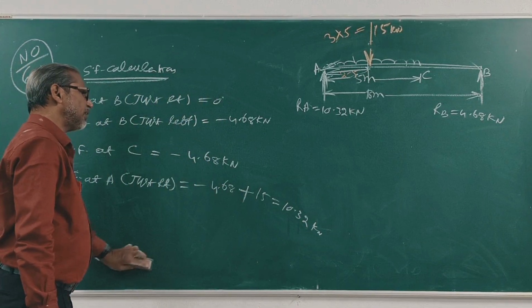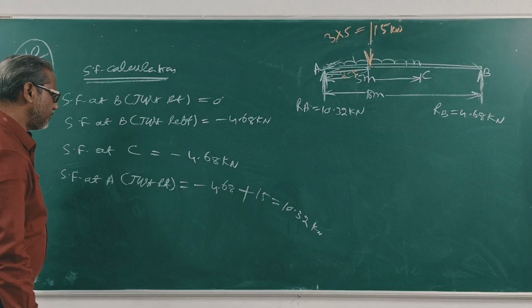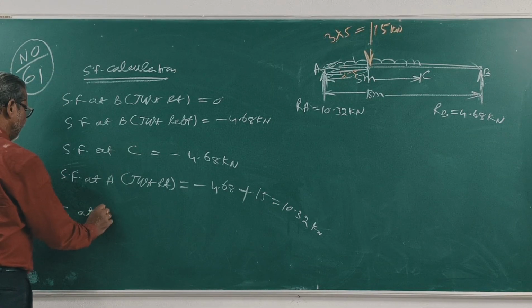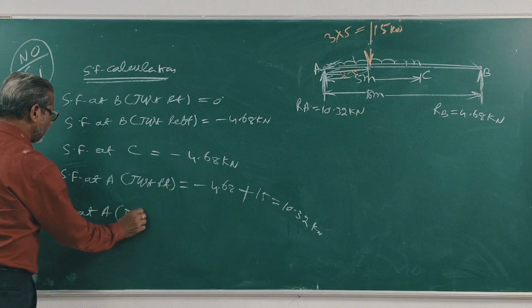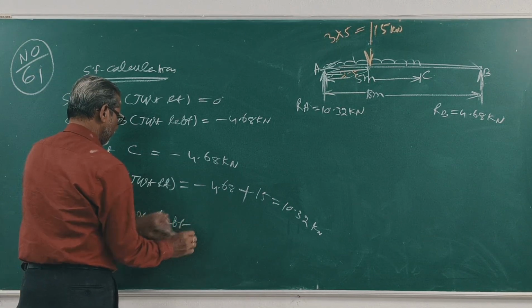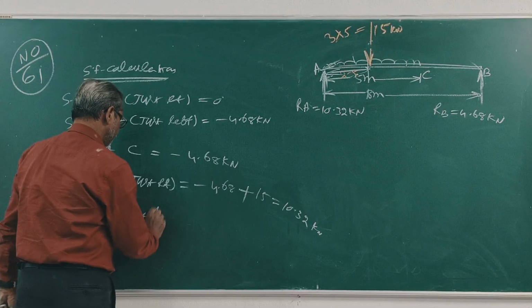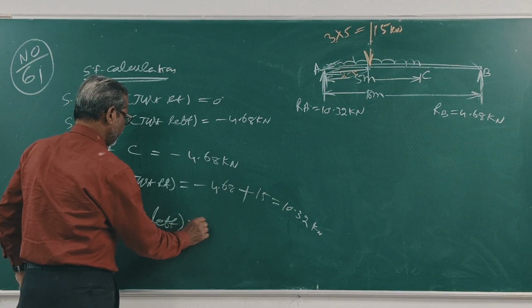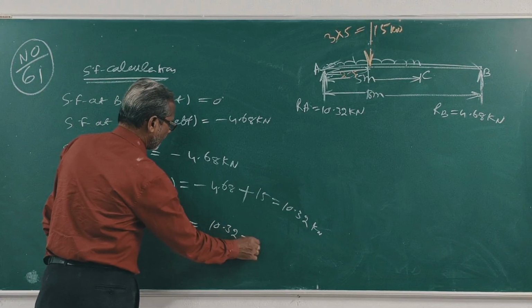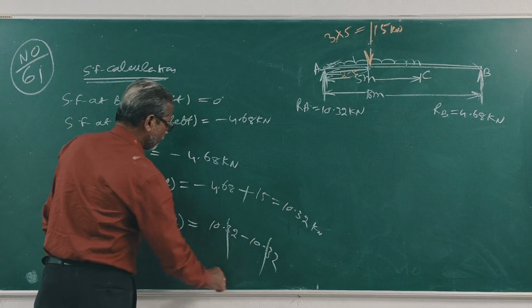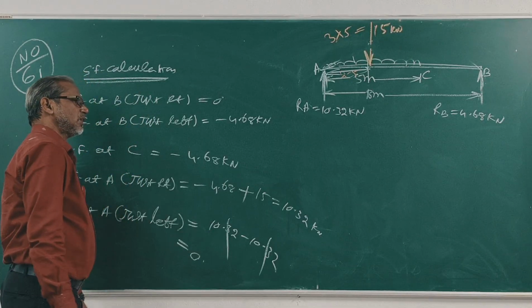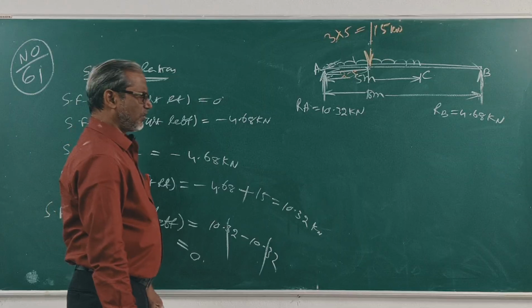At A just left, shear force at A: 10.32 minus 10.32, 0. Clear? Now draw the shear force diagram.